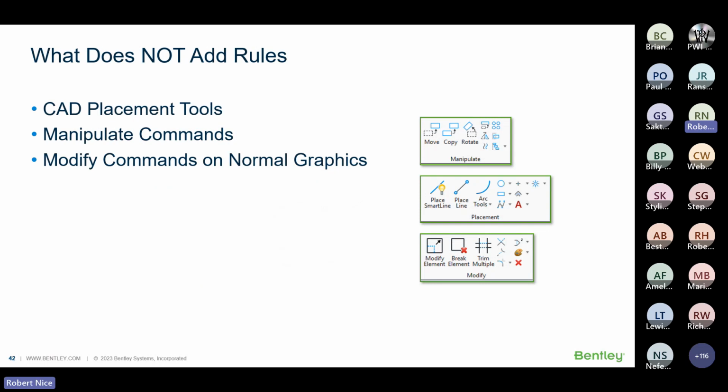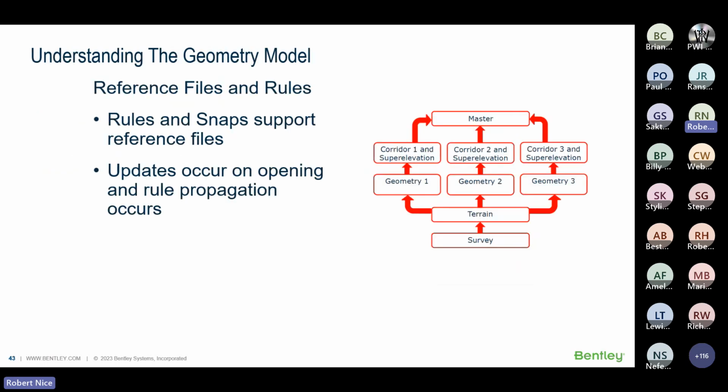What doesn't add rules? Basic CAD. If I just draw a line in MicroStation, a smart line, there's no rules added. If I break that smart line or modify it, nothing happens. So modifying normal graphics will not add any rules. You have to use the civil elements.